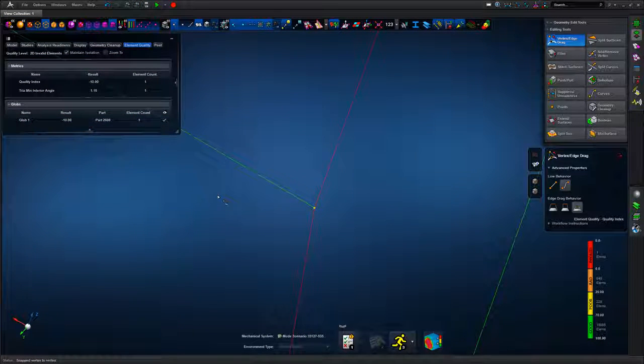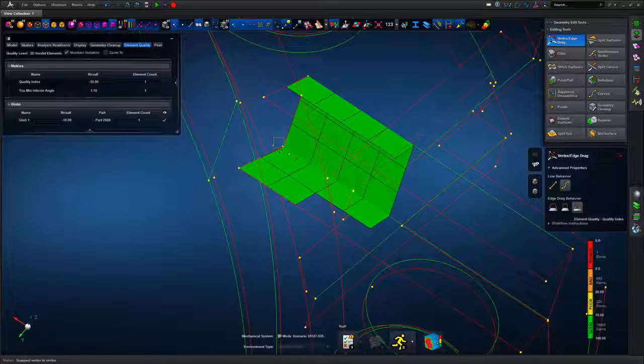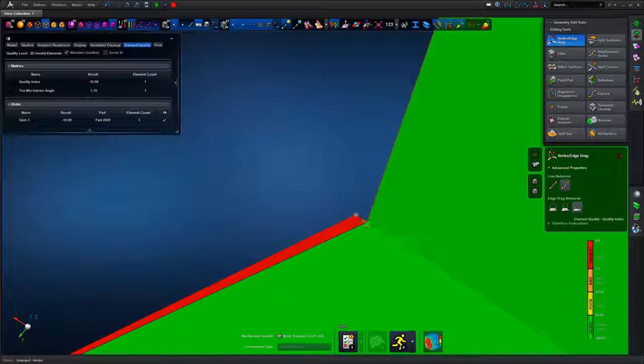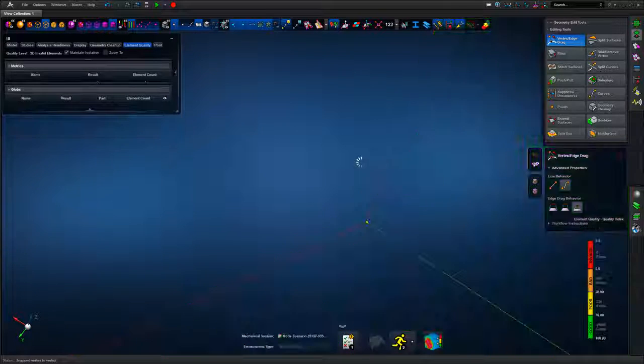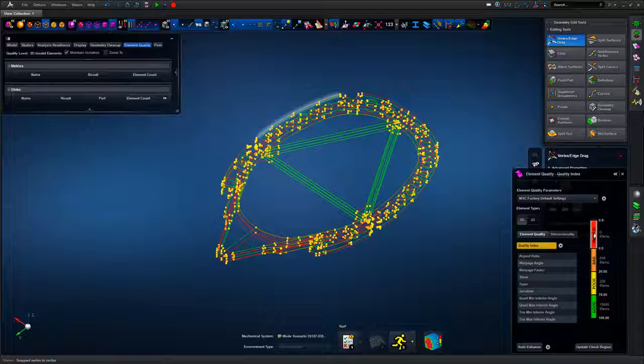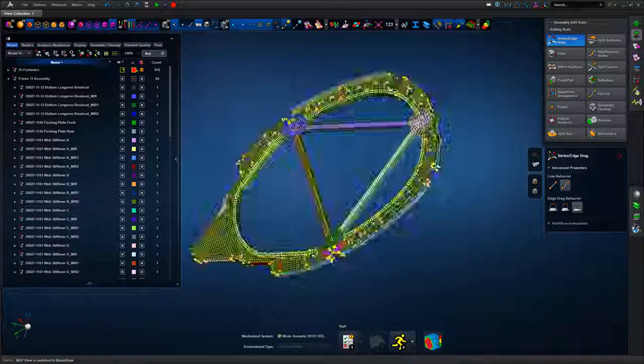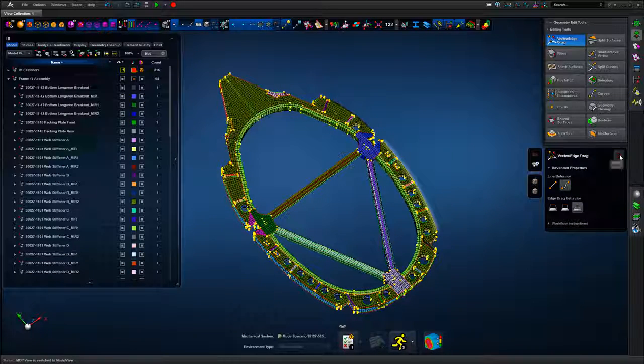We could perhaps tailor some of the mid-surfacing operation to work in a slightly cleaner manner, both from a defeaturing and a resultant mid-surfacing definition. But obviously we just hit this model with quite a broad set of parameters just to show the overall technique that we would use for that definition.